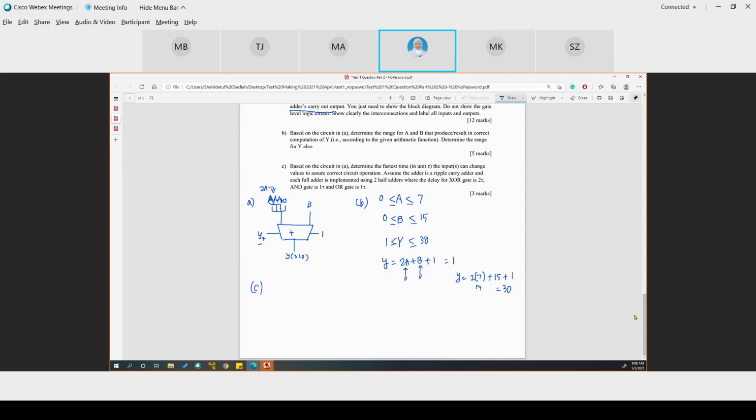Right? Yeah, but I understood it as if it is a correct result, then you take the whole thing. So like A, you can make it 5 bits. So A 5 bits? No. A is 3 bits. The original A is 3 bit because the LSB is 0. It's a 4-bit adder. Yeah, but the question is to produce the correct result. For me, I did the same as Jack. I added another full adder to the end. So you understand it wrong.